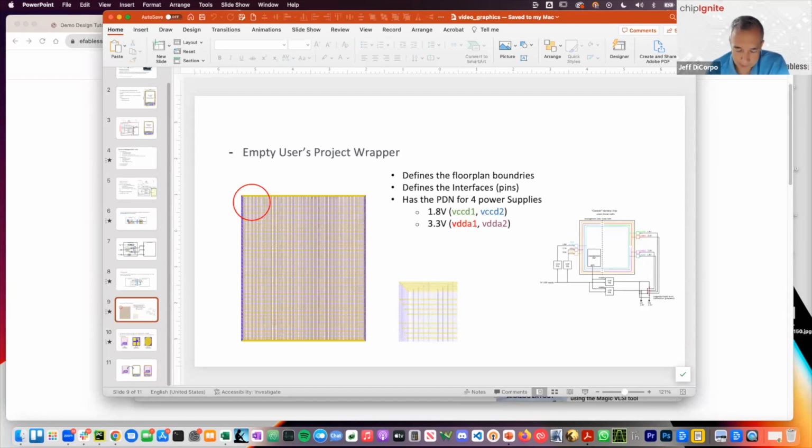The other option is through the logic analyzer probes that I mentioned, right? There's a set of 128 logic analyzer probes that provide the ability to directly monitor or drive signals to your project. That would all be under the control of the RISC-V processor, so you would implement firmware to drive that functionality when you're operating your design.